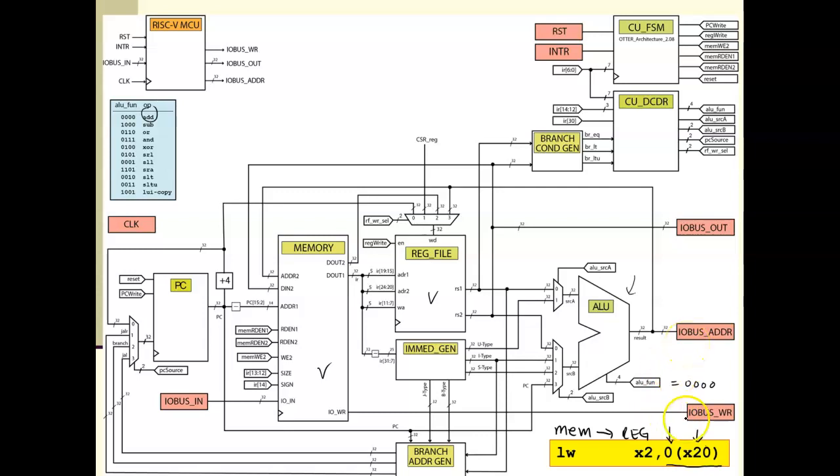Okay, so this offset value here is actually the immediate type, and this is actually RS1. I know that from looking at the spec, and so essentially RS1 goes into this register, which is going to be a 0, and then this is L, the load type instructions, which I looked up, and sure enough, it's an I-type instruction. I had to look it up. I didn't really know what it was, so I need to select a 0 and 1 to get that immediate value to add with the base register.